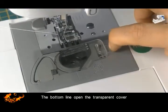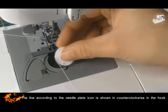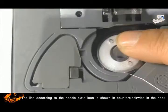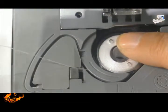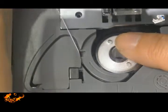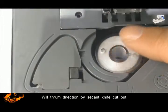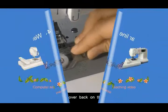For the bottom thread, open the transparent cover. Place the thread according to the needle plate icon, counterclockwise in the hook. Pull the thread toward the thumb direction through the cutting knife to cut it. Put the transparent cover back on the bottom thread.